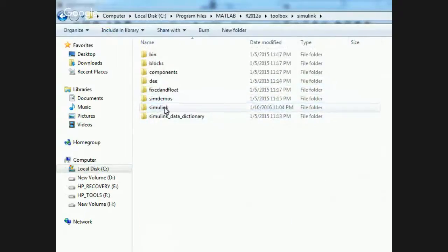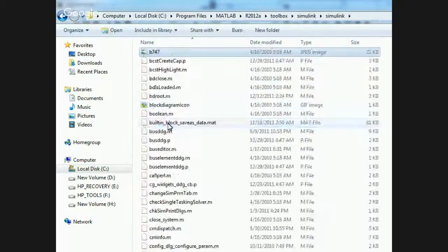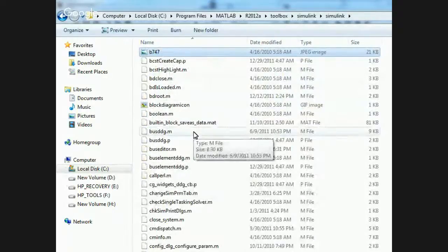In Simulink again, one more Simulink. So that B7, this is that aeroplane picture, B747. Same location you put your image, whichever image you want. See that the resolution should not be very high. Normal resolution. It is not like a very high pixel picture. If you put it, sometimes a question mark will come there. And the other thing is, once you put the image also, sometimes it will not come. You have to shut down your system and then restart it. Then only it will come.